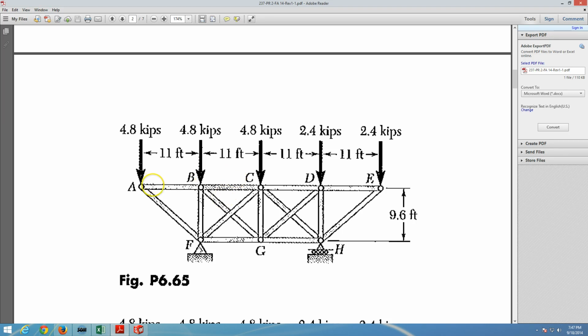In this exercise we will create this model, number 1. A very important thing is to start building it inside SolidWorks as a part with the IPS units. When you type a dimension, after 11, type FT, which will automatically convert it to 11 feet. There is also a node here, so it needs to be aligned up to a middle, otherwise it will create an unstable solution and a geometrically impossible solution in a plane.